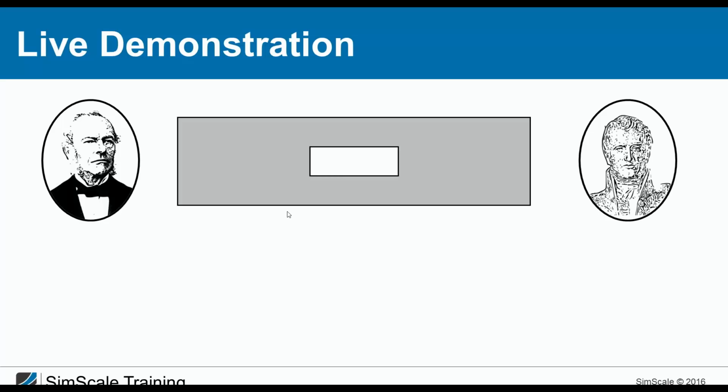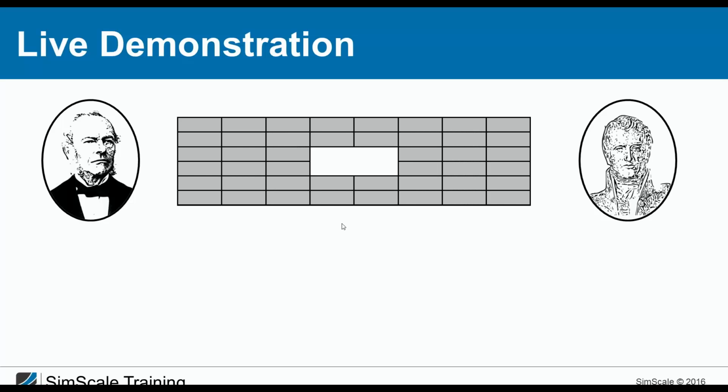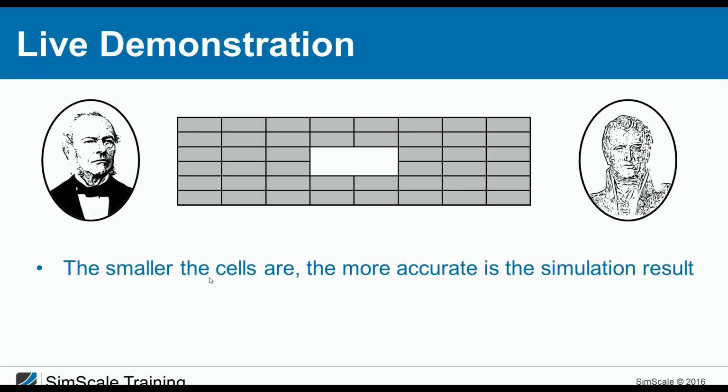But what can we do right now? That's a very simple idea. Just imagine you want to simulate the flow, and this gray is our flow field around this body. You cannot solve this equation analytically. What you do is solve it numerically, which means you divide your fluid domain into very small elements, which we call cells, and then for the center of every one of the cells, you calculate quantities like pressure, velocity, and temperature.